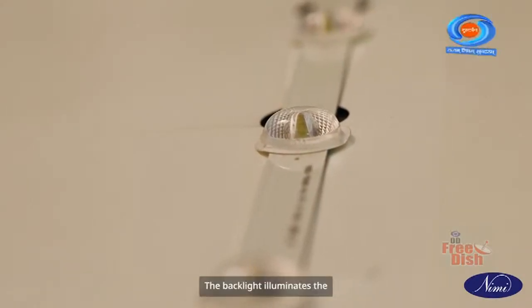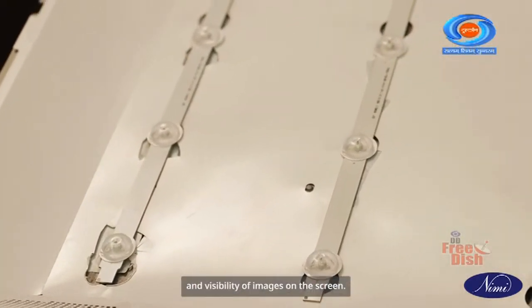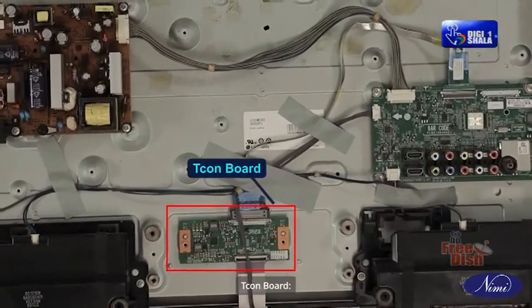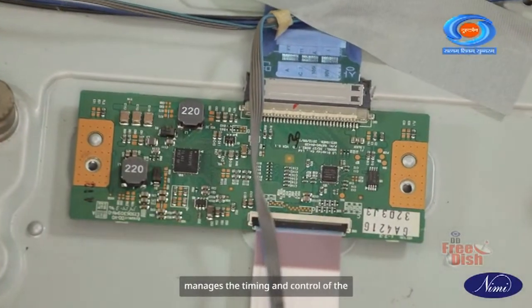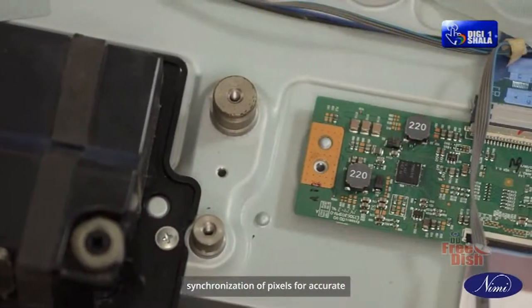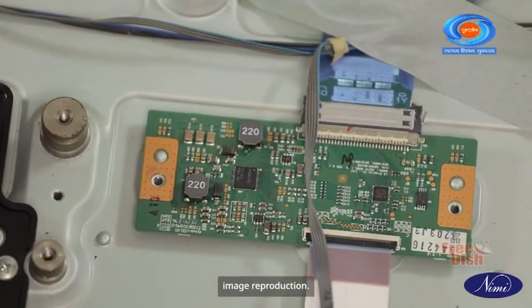Backlight. The backlight illuminates the display panel, ensuring brightness and visibility of images on the screen. T-con board. Typically placed at the top center or back of the TV, this board manages the timing and control of the display panel, ensuring proper synchronization of pixels for accurate image reproduction.